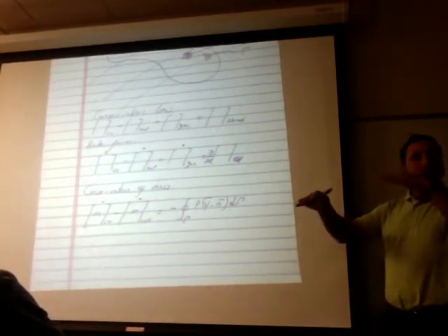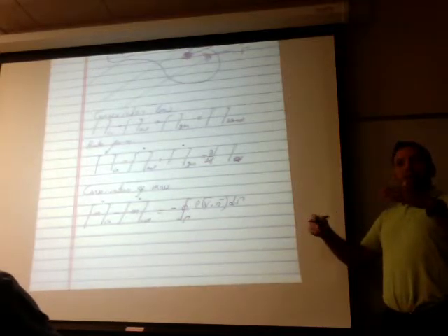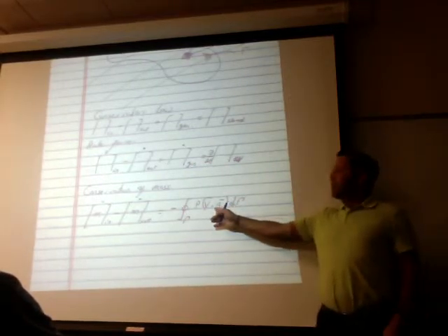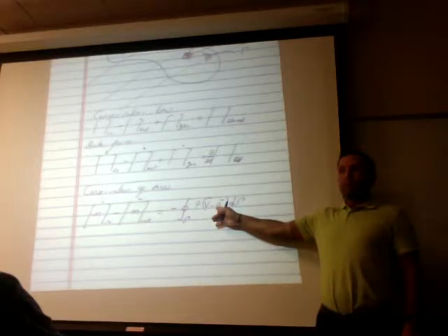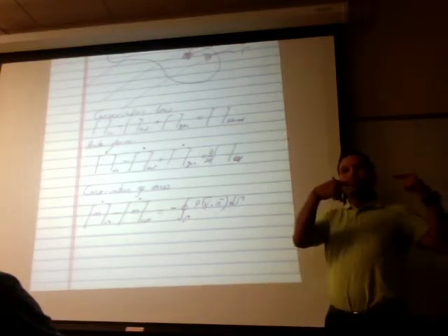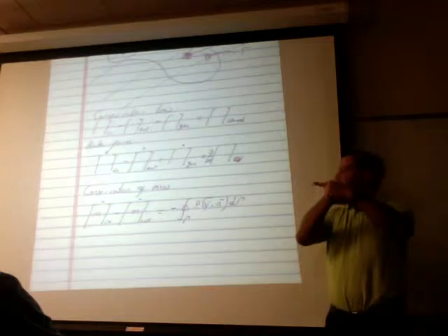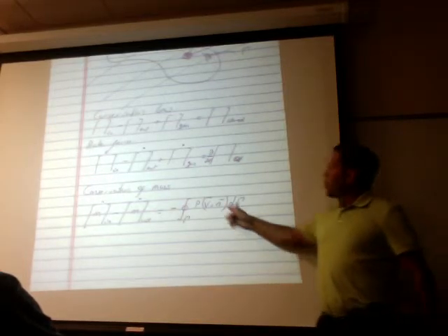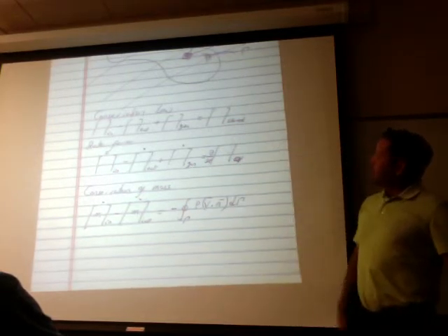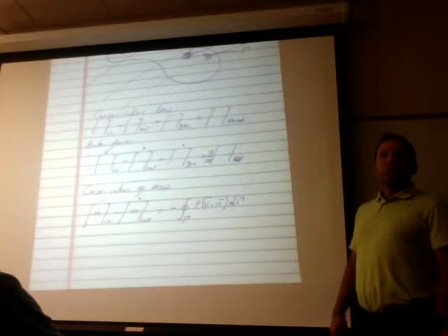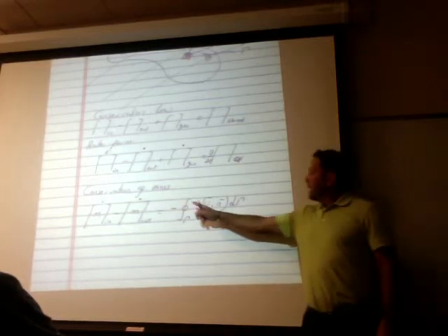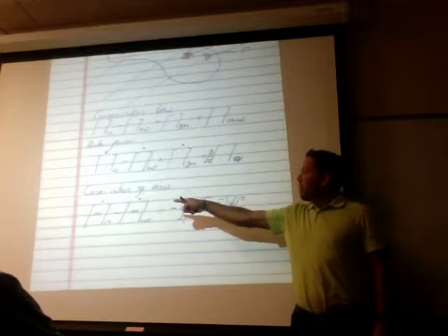Like in the walls of a pipe, for example. In the walls of a pipe, V dot n is equal to 0. At the inlet of a pipe, V dot n is negative, right? Because the normal vector points out and the velocity is coming in. So they're opposite to each other. All right, so the total integral over the entire boundary that surrounds this domain, the negative of that is the amount of stuff coming in minus out.